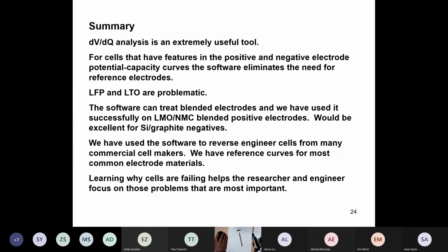If you put it outside of the jelly roll in the electrolyte, you'll learn that it measures voltages that don't make any sense, because there are large electrolyte concentration gradients that appear in the region of the cell near the anode overhang, and that leads to faulty voltages.